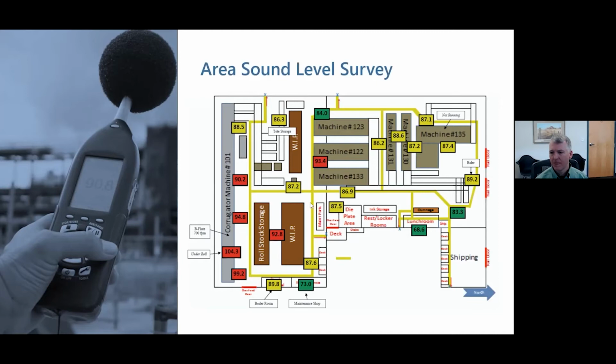If you're doing one of these, I would also monitor locations that don't have a lot of noise, just to document that in a certain area, like a warehouse area of the plant, it's only 65 or 70 decibels, so we're not going to have to require hearing protection in those areas. It's also important to note that some plants have consistent noise levels in an area, but then a big air compressor that kicks on and off. If you have some intermittent noise source, you need to document that and make a note on the maps, like, it's 95 when the air compressor's on, but it's 85 when it's off. The more information you have on there, the better. And these meters should also be set to A scale, which is going to come from the factory that way.